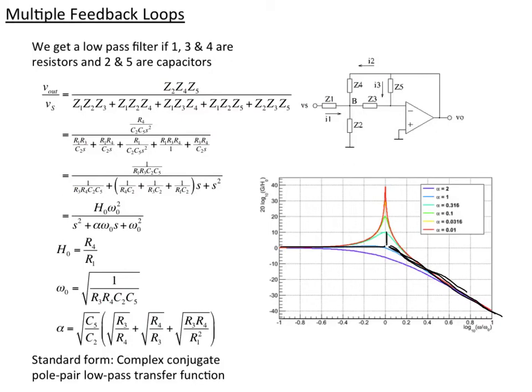So if alpha is 0.1, then we have a gain of 10 there, basically. And that's, in fact, this case. And then we take the log 10 of that, multiply by 20 to get 20 decibels there. So that's how you make a Bode plot of this, and then you estimate this gain.